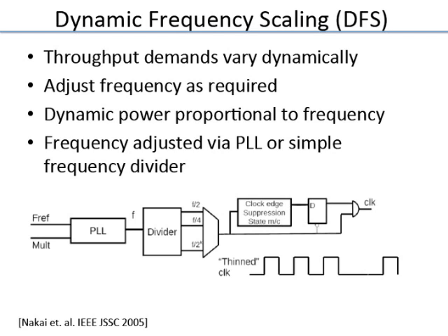This clock I'm using for some device, and there are set and hold times for the device. The point here is that you have to make sure that the device, when it's running at f by 2, has critical paths that are able to run at f by 2.